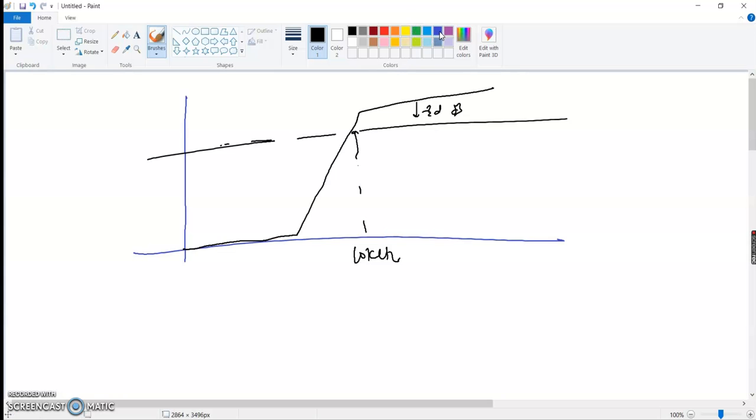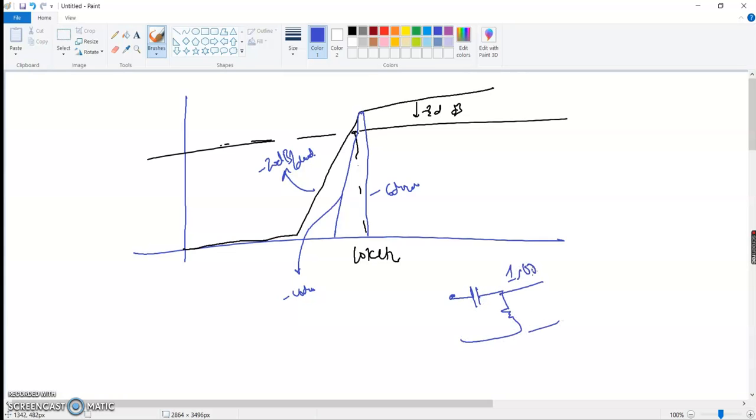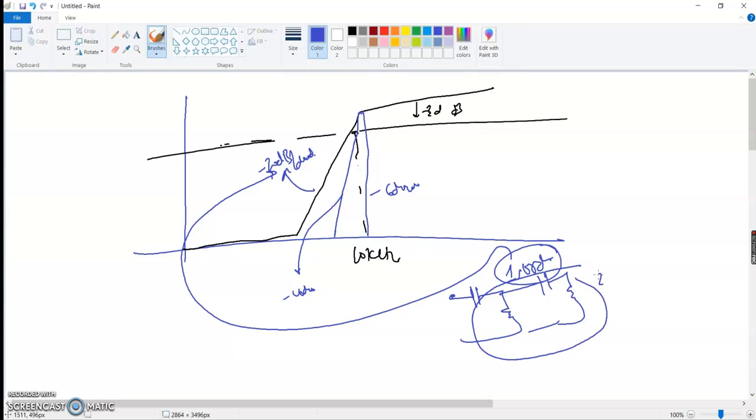Now, again, if you want to increase the sharpness of your falling edge, for example, this one black line over there is a negative 20 dB per decade, right? So if you want to achieve minus 40 dB per decade, or minus 60 dB per decade, like in the last lesson, you can just have a higher order of the circuit. We designed the filter which is like this, which is first order, so it will give me a negative 20 dB per decade. But if I cascade it with another capacitor and resistor, it is now second order.